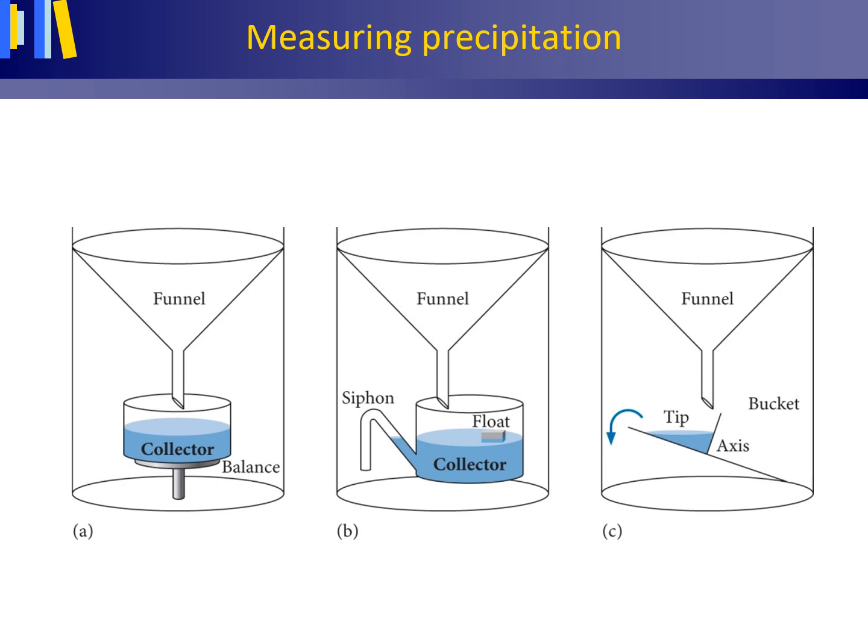It is probably useful to mention a number of the problems that one can encounter when measuring precipitation. When placing a rain gauge in the field, one should take care to ensure that the rain gauge is well exposed. For instance, that the distance from a high object is sufficiently far as not to be measuring in the high object's rain shadow.